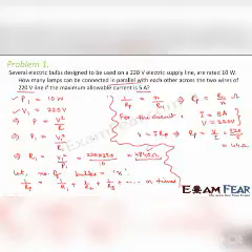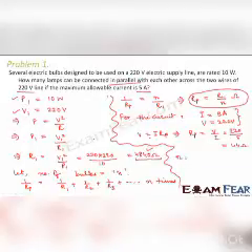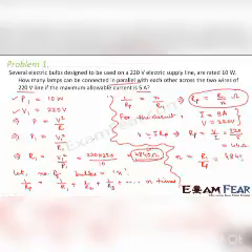So now we make use of this equation and we say that n is equal to R1 by Rp. R1 was 4840 ohms, so put it as 4840 divided by 44. This comes out to be 110. So that means in order that a current of 5 amperes flows through this circuit, we will have to connect 110 electric bulbs in parallel with each other.